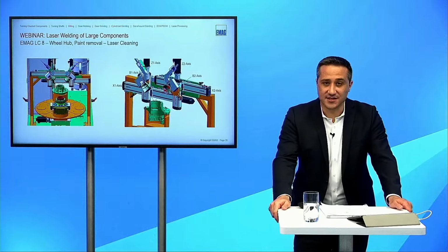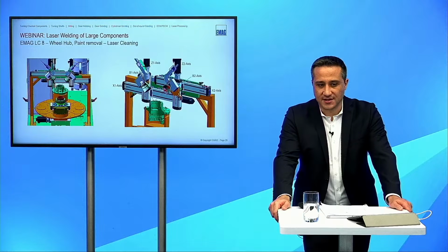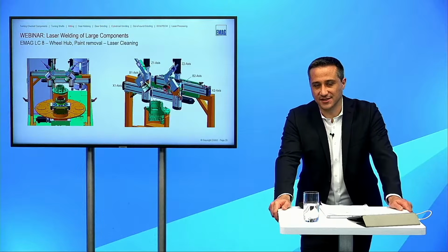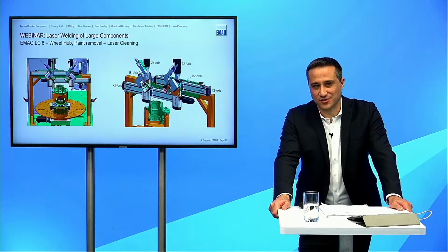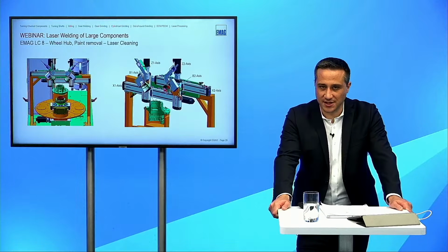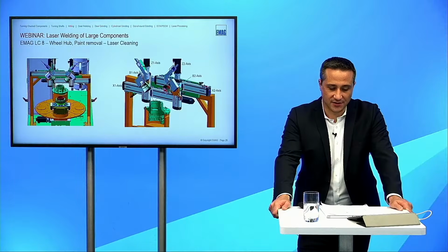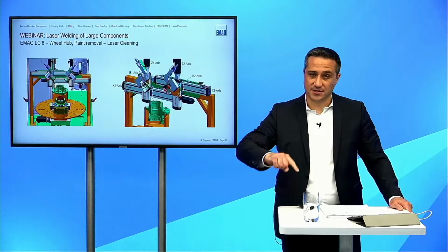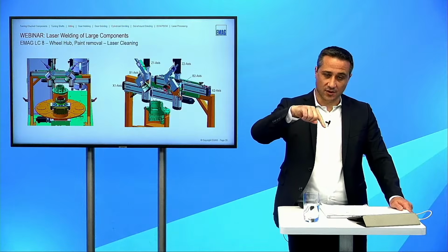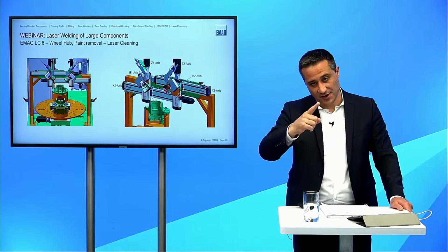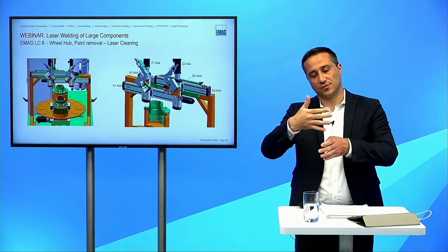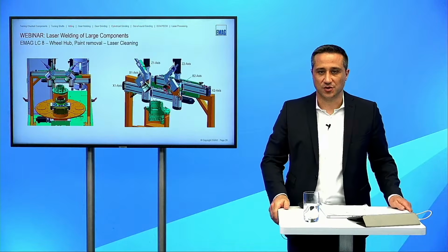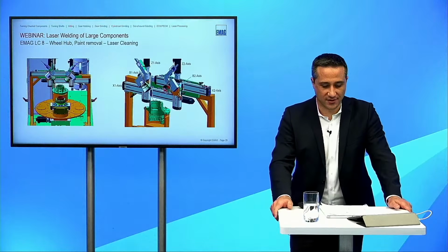We realized that at the very first testing, and then we started to figure out how to make sure that this will not have any negative effects. The answer is we decided to have an own developed system in the software, and this software is able to move the optics or the laser in a very defined way to make sure that there will be no overlap in between, so that there is no heat affected zone.